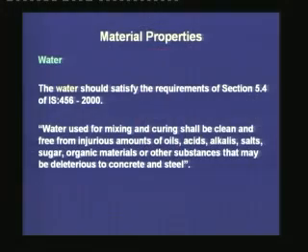added. The water should satisfy the requirements of section 5.4 of IS 456-2000. The code clearly states that the water used for mixing and curing shall be clean and free from injurious amounts of oils, acids, alkalis, salts, sugar, organic materials, or other substances that may be deleterious to concrete and steel. Potable water is accepted for constructing concrete.